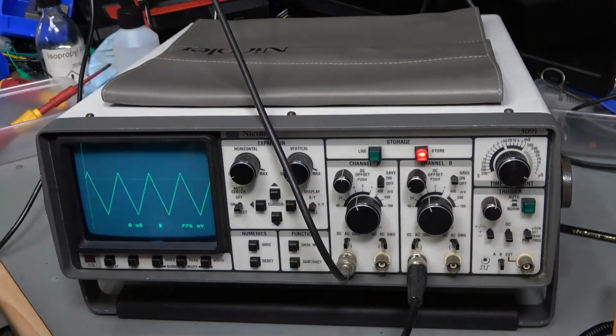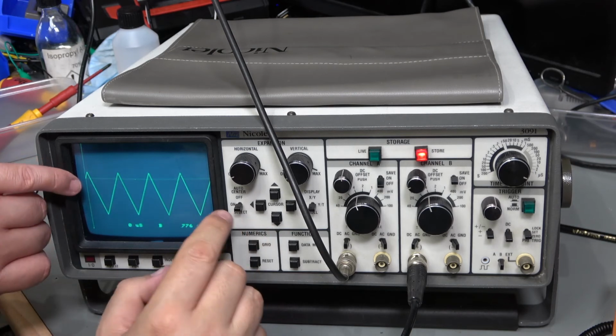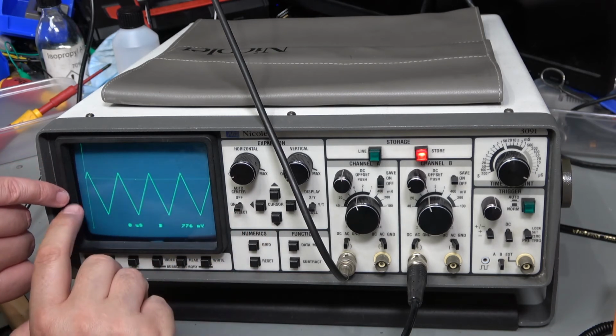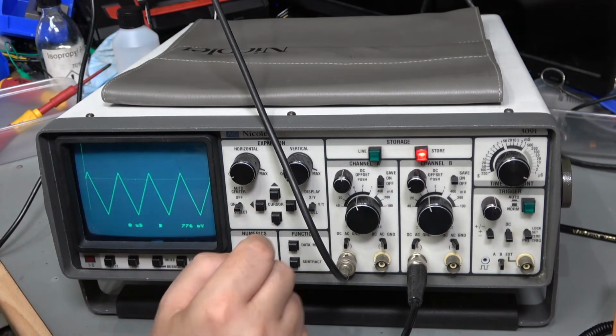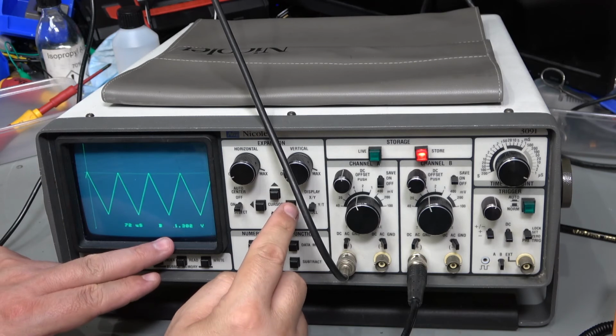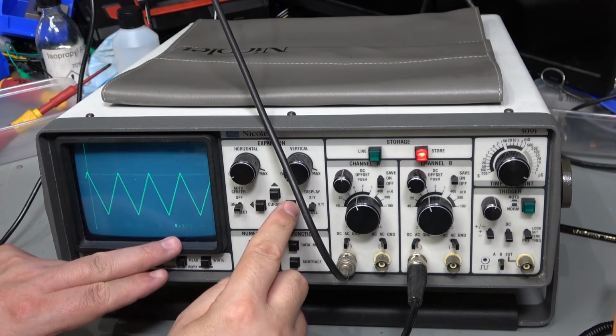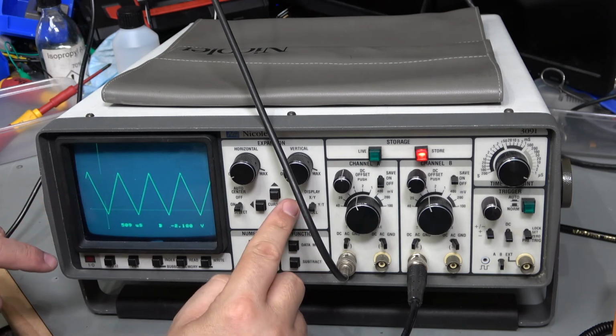So if I store that, I should now be able to move. I've got auto center on, so I can see that currently the cursor is set on the left hand side and it says 776 millivolts. If I scroll that across to the peak, 1.302 or thereabouts, then I can kind of move this up. I can move it faster if I multi-click it.